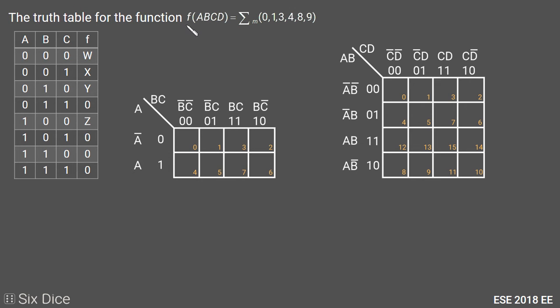One K-map is for the function of a, b, c, d, which is a 4-variable K-map given in minterms. The second K-map is a 3-variable K-map, given as a function f here, and we will put w and the function f values in this 3-variable K-map. For the 3-variable K-map, I choose a as the most significant bit and c as the least significant bit, and the numbering of cells uses a as MSB and c as LSB.